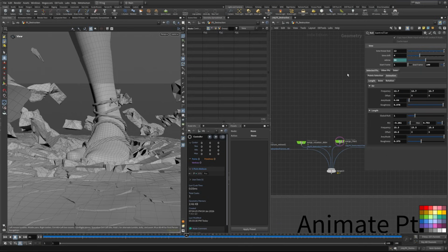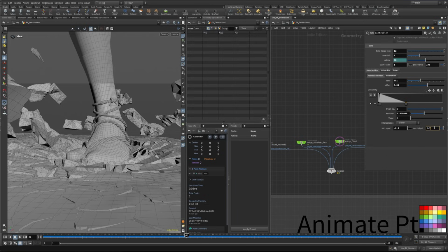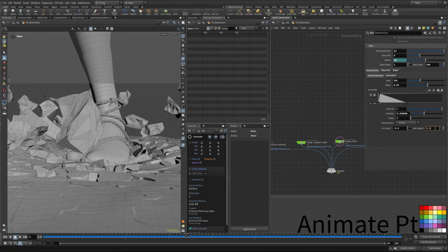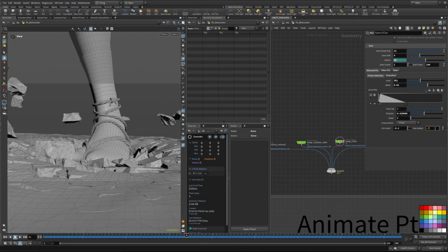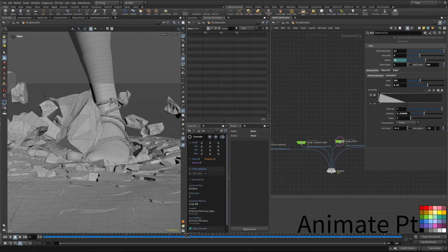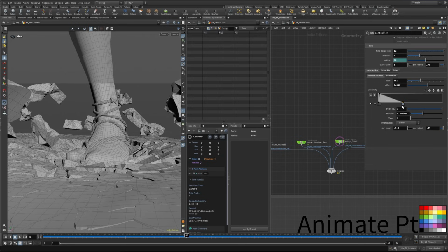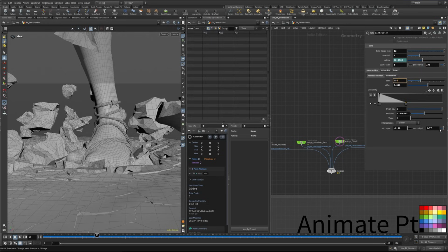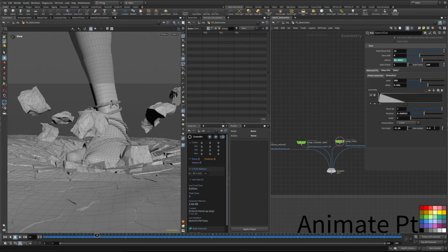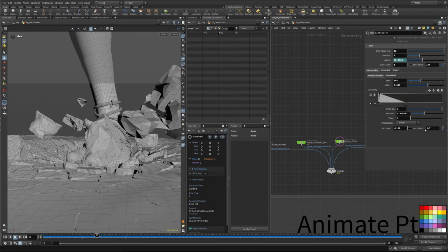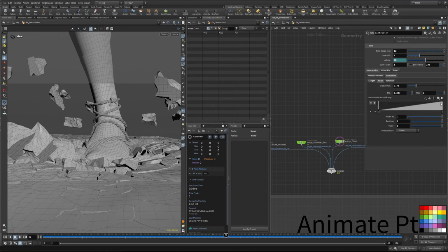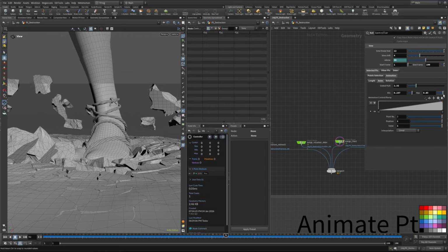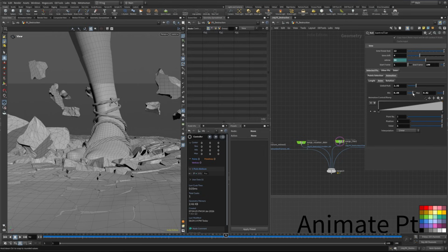Maybe a little bit too much of the debris stuff here, so we can lower it a little bit. So let's go to our point selection, and we can use a value of 0.8 or 0.7, 0.79 maybe. We can also move this here a little bit around. I don't like this debris thing over here, so let's use another seed. I think I even want even less, so maybe 0.65, or just 0.7. Now let's also change the height again a little bit. So this time I want to decrease my maximum height, but increase my minimum height.